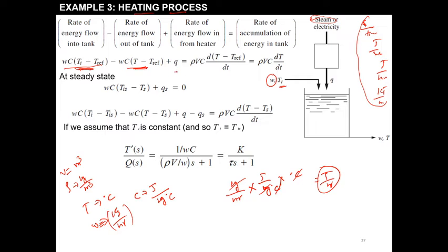And what is this Q? Q is the heat supplied to the tank, so it is again joule per hour. Now come to this point. What is being held inside the tank? Ultimately the temperature is going to rise with the help of this heating material. So the accumulation is a change in temperature with time. Therefore we have written dT by dt, and when you multiply with rho V C, it again comes to joule per hour.